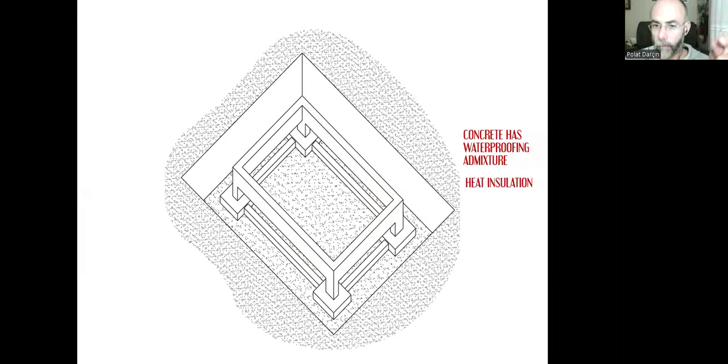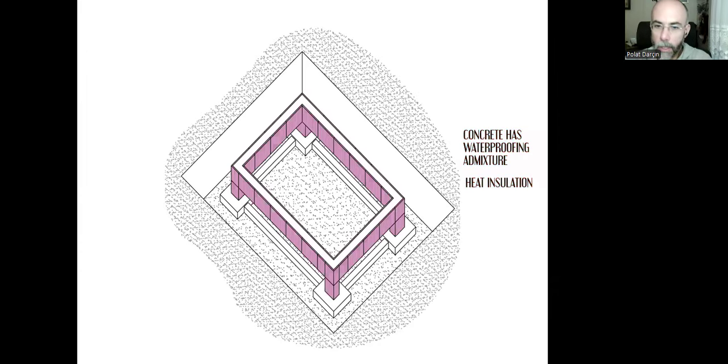And for the heat insulation, the components above the frost line, that means the components above the footings, need to be covered with a proper heat insulation material, and that can be EPS or XPS. We can use those boards, 5 centimeters thick, to cover the 4 sides of the foundation columns and 3 sides of the grate beams: the outer side, the inside side, and the underside.